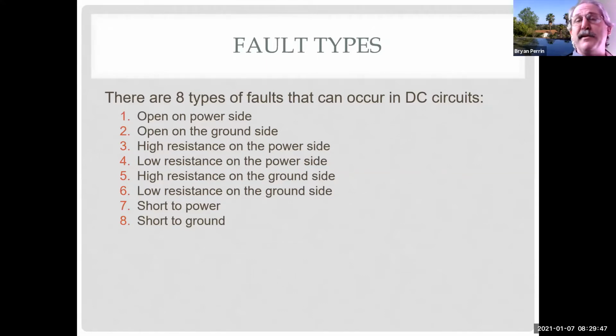I was able to figure it out very quickly because I know how circuits have to work. I know a fuel pump needs power and ground. Where is it coming from? Well, ground was right next to it. Power is coming from the computer. Well, let's see if the computer is giving it power. I checked, is the computer getting power? Well, the computer's getting power, but not giving power. I'm going with it's a problem. And actually, I was able to test it. It's got a bad transistor in it.